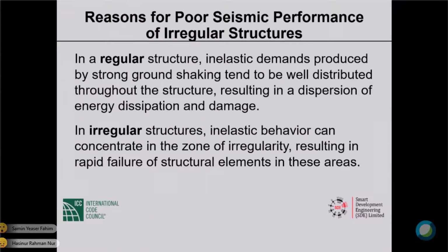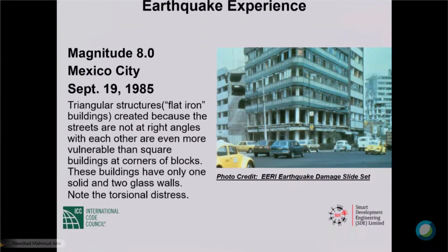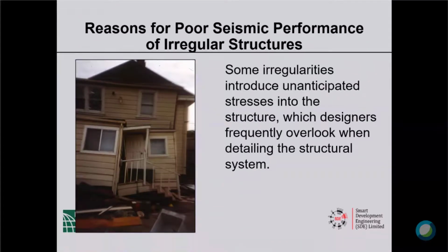And what we are saying there, I think, may even be common sense. So take this building. The left face has shear walls, the back face has shear walls, the front faces do not have any shear walls. So earthquake forces will gravitate to the strong elements, which are the shear walls. So those shear walls at some stage will begin to yield. Okay, that goes without saying. And when the shear walls begin to yield, the loads transfer from those yielding elements to the frames. And you will not capture that out of elastic analysis. There is no way. Okay, so that's what we are trying to say on the slides that I was on.